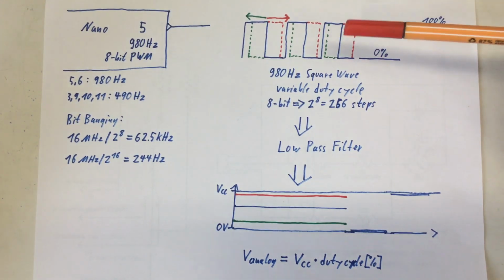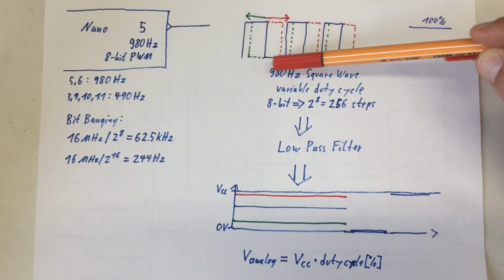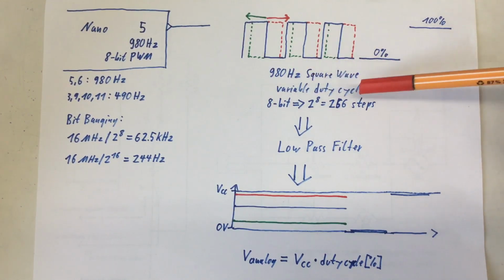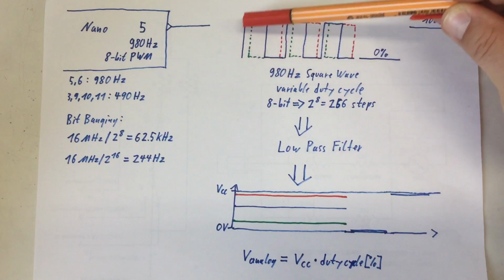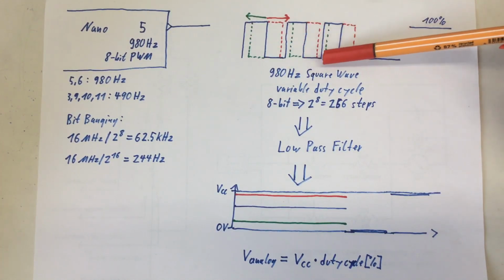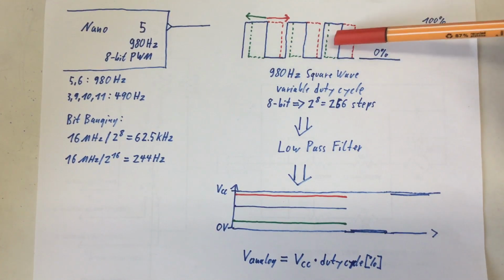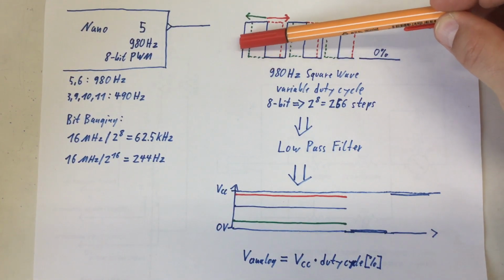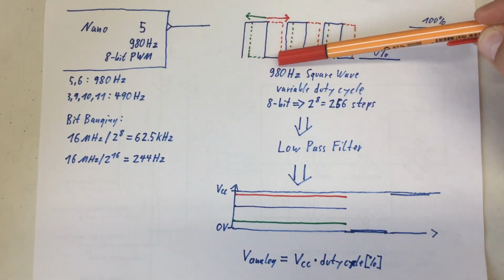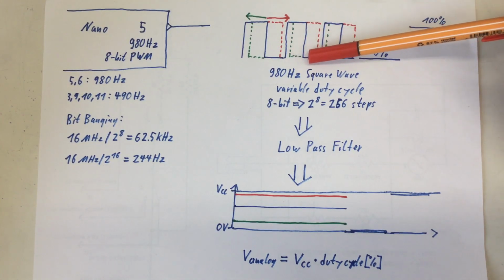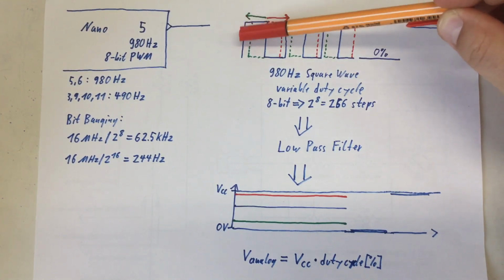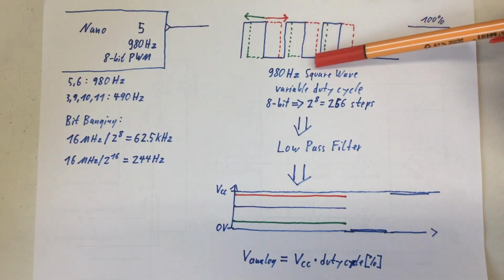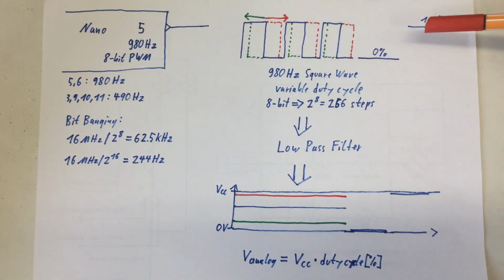Talking about PWM signals, these are basically just square waves where you can vary the duty cycle, okay? So this is the blue line, a 50% duty cycle square wave, and in PWM you can either shorten the duty cycle, following the green line here in between, or you can lengthen the duty cycle following the red line here. And there are 2 extremes.